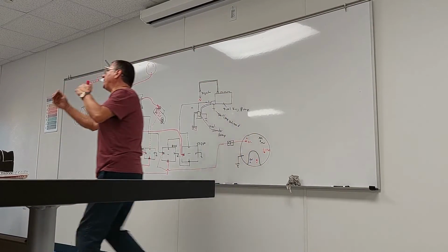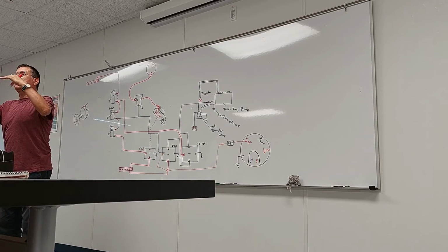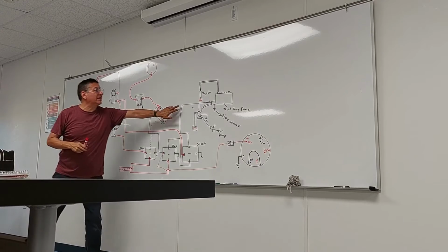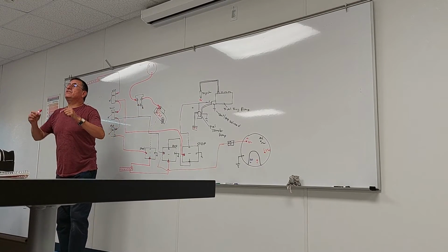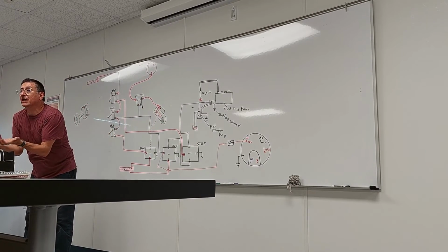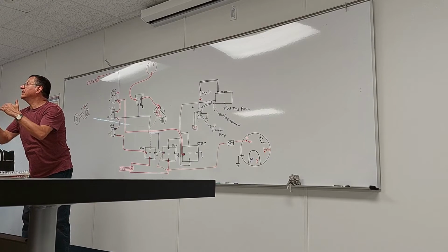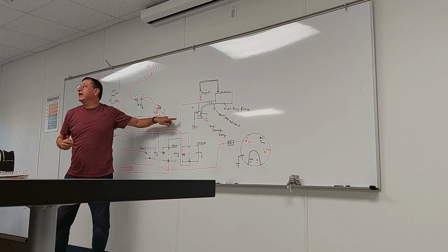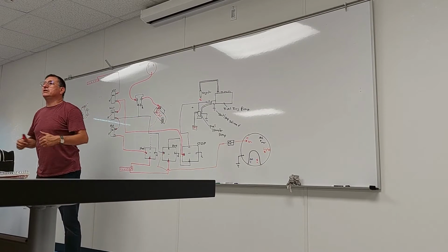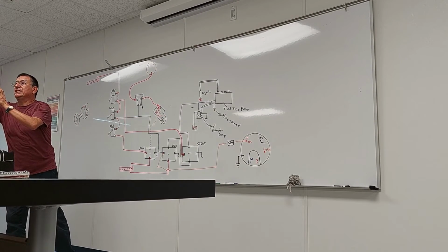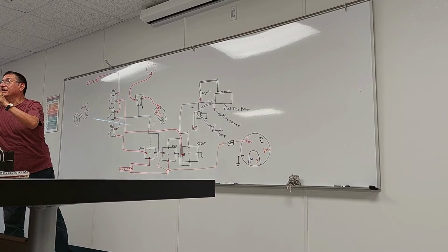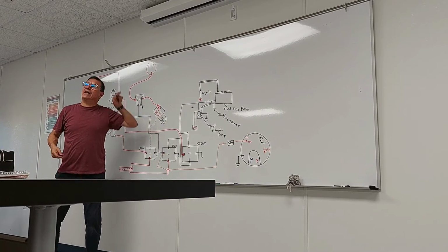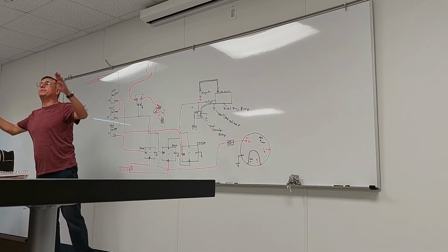If the temperature of the engine passes the limit, that switch opens and interrupts that cable. If the pressure of the oil internally in the motor decreases past the limit, it interrupts that cable and stops the engine. Or if the temperature in the exhaust elbow, you remember, passes the limit, it interrupts that one, interrupts the fuel and stops the engine.